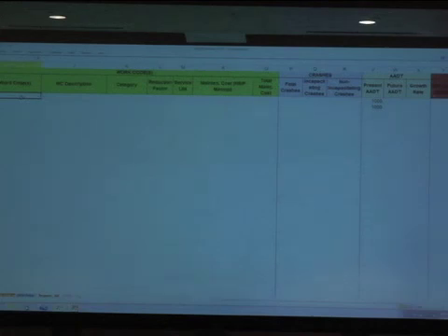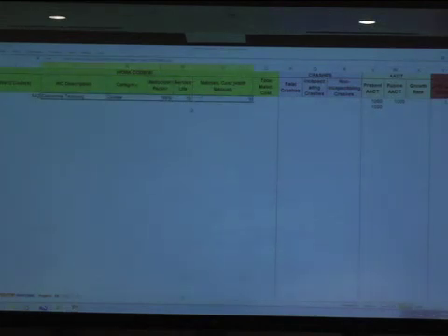So let's assume for a minute that we identified by using the Google Earth layers a project, and this project involves centerline texturing. Here you can either select by using the drop-down menu the specific work code that you're interested in, and then the spreadsheet automatically populates for you some important items that go into the SII calculation. So you don't have to look at the text manual and manually enter these numbers into this formula. These fields include obviously the work code description, the category where this specific work code belongs, the reduction factor, service life, maintenance cost, and many more that are not shown here.